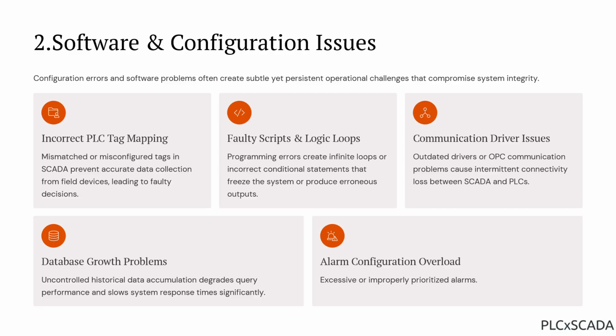Now let's say for one of our clients, SCADA was running fine for almost 3 to 4 years. One day the SQL log file reached more than 50 GB. It was filling the C drive because the software developer had configured SQL Server and stored it on the C drive. So it reduced the operating system's free memory, and SCADA stopped logging and data was lost.